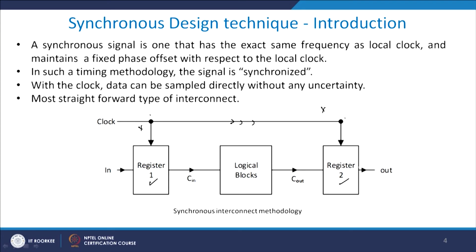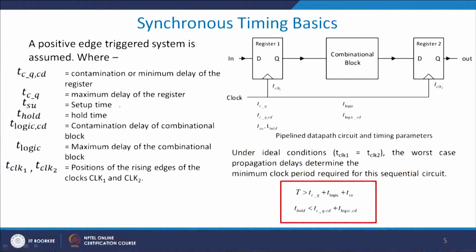So when you are trying to insert data between the clock and the input and output registers, you have to ensure that the data is available for evaluation at least one setup time before the clock edge. We will discuss basic synchronous timing issues here, but we will not go into details. If you remember, we have already discussed setup time and hold time.